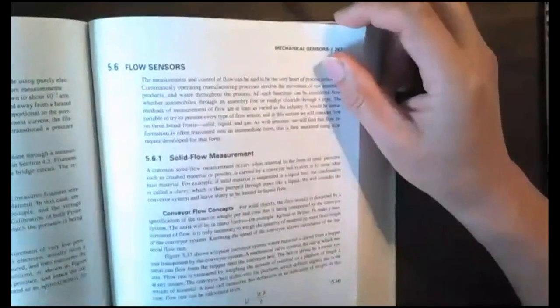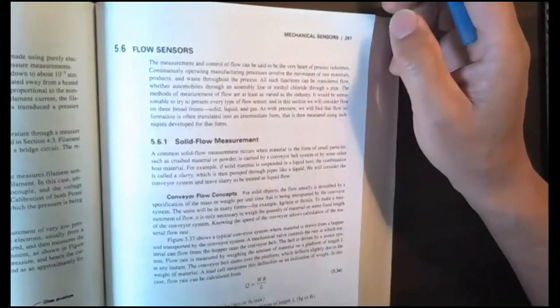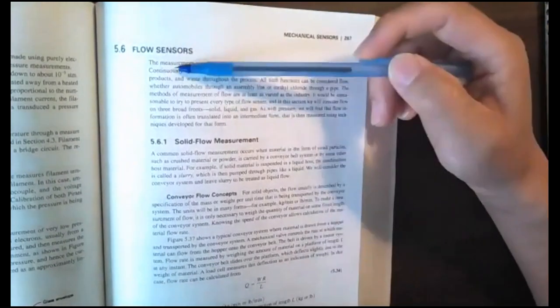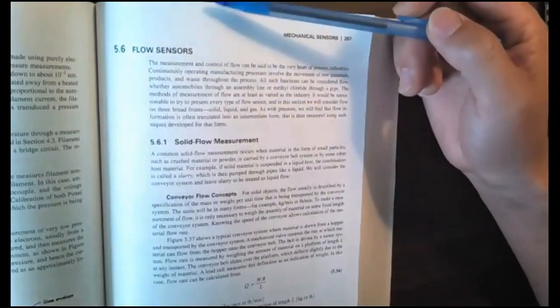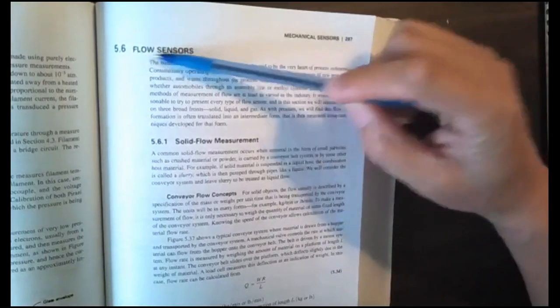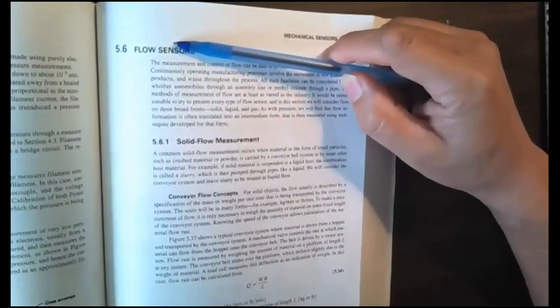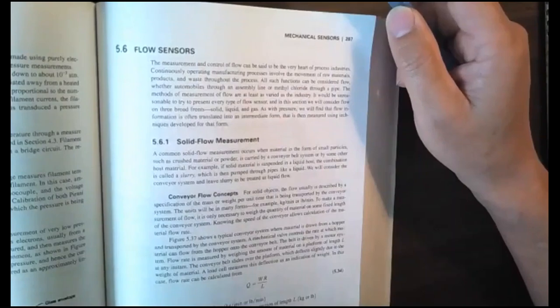So that's the third type, right? The last type will be the flow. Flow sensors, all these sensors are popular. Craig is talking about changing the augers to change the flow. But ideally, you not only want to change the auger, you also want to put a flow sensor to measure how much is the flow, like a gallon per minute or 2 gallons per minute flow sensor.